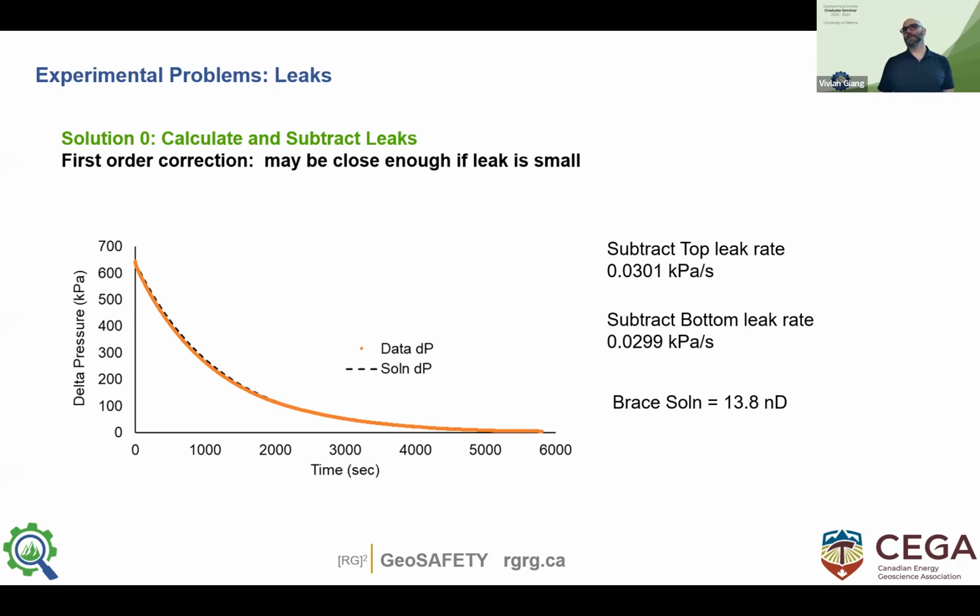How long did it take us to get to a point where we could run a test? About 7 days, seven to 10 days. First the specimen is completely vacuum dried, so there's no water in there. Then we put it in the cell, load it to about 500 kPa effective stress, and sweep it with CO2 to remove any air.